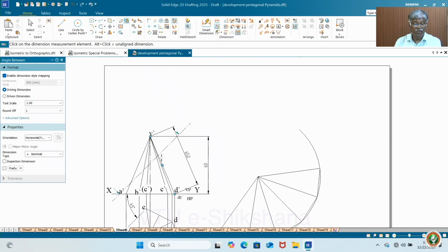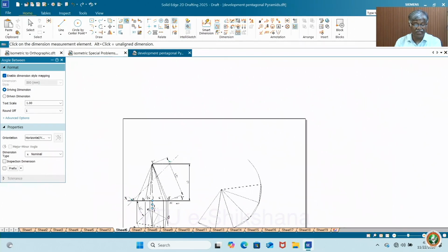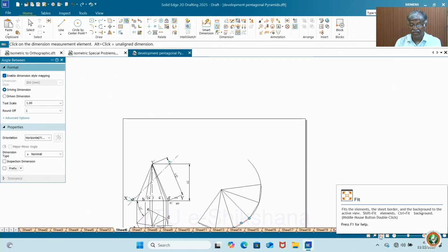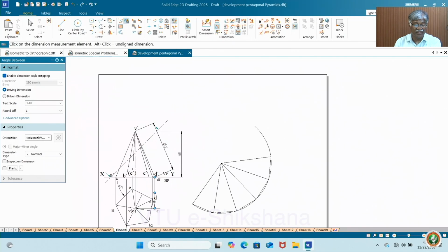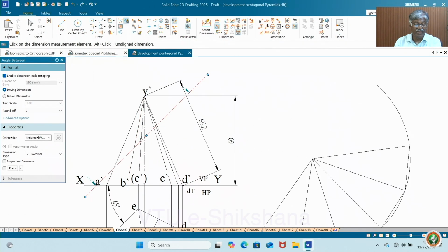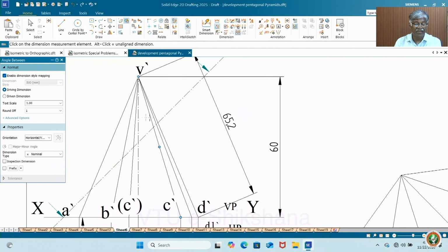Okay. Now, after drawing the section plane, you try to dark the remaining portion. Here there is a little confusion, I will tell you what confusion. Very close lines are there. See here, because of the inclination, C and D and true length all are there. You must do it carefully with patience. This is 1, this one is 2 and E you should not give right now. Then you have to give for C, then D, then E, similar to the one which I worked out, same type.